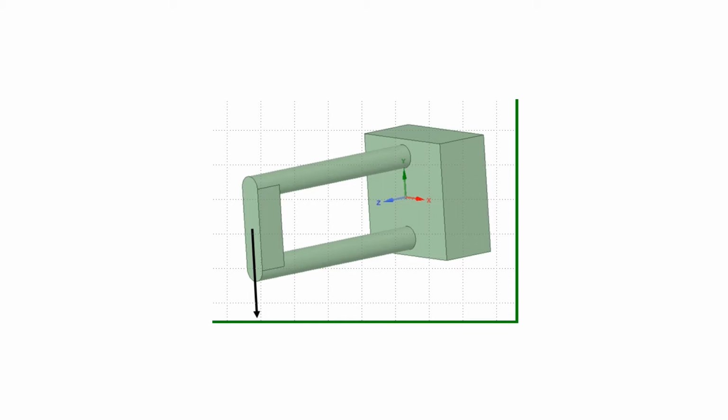Ansys can efficiently vary the specified geometric and material property values and compute the associated results without redrawing or remeshing the structure. Ansys can also determine the correlation between specified inputs, such as geometric and material property values, and specific outputs, such as stress and deflection.